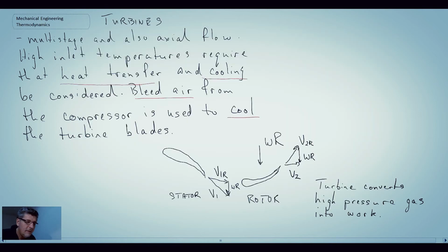So you could see from the turbine blade that we had a coating on it, and really that is the area of increasing the efficiency. There are a number of different areas. You have the combustion section, you also have the performance of the compressor, but in terms of the turbine, places where we can have efficiency enhancements are in terms of enabling the turbine blade to take higher and higher temperatures.